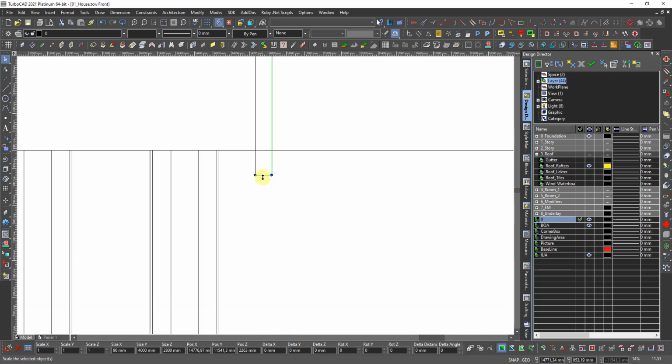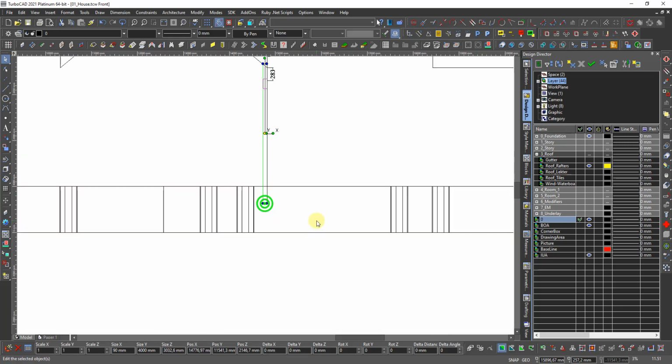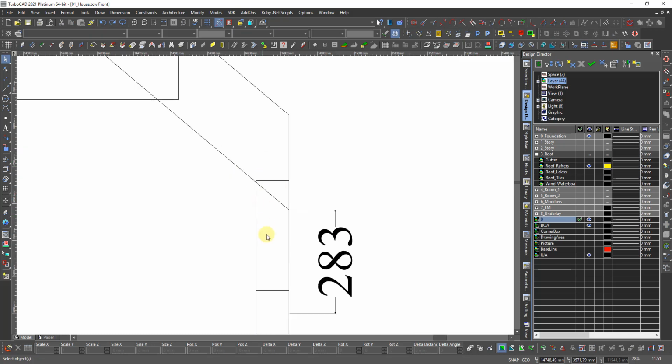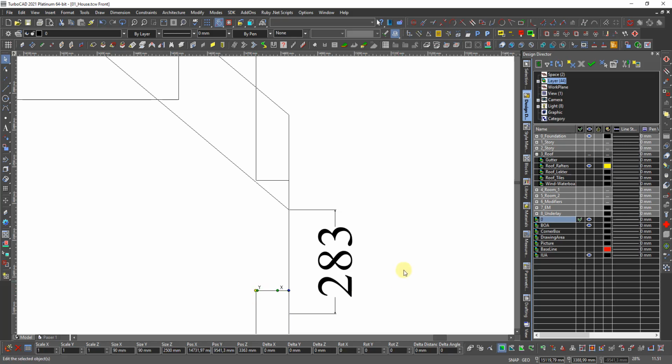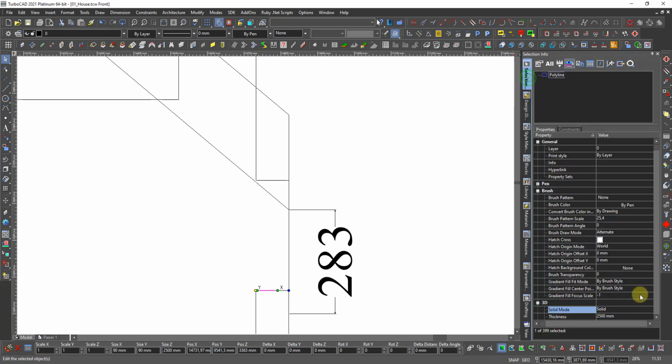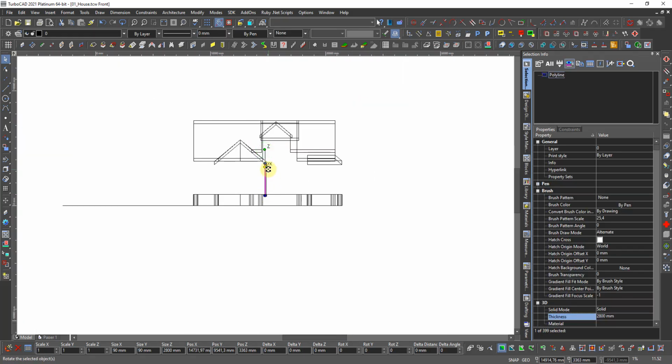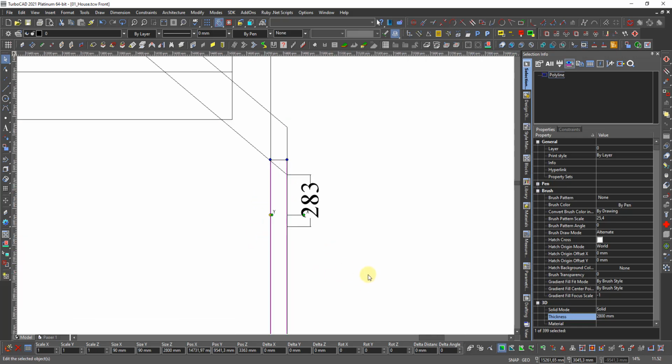But now they should go more down. So I take this and drag it more down. About there. That was not possible. Control set. This D in V, and I go to selection info and I change the height to 2800. So then it go down again. Now it didn't, because I have reference point there and it lifted up. So I move it down -300.